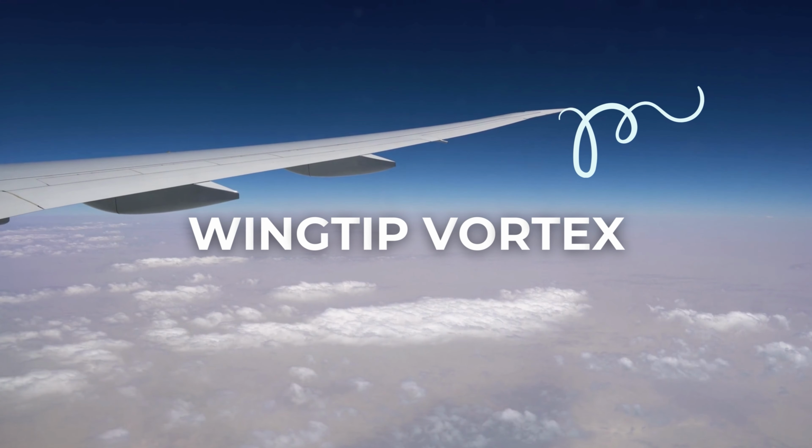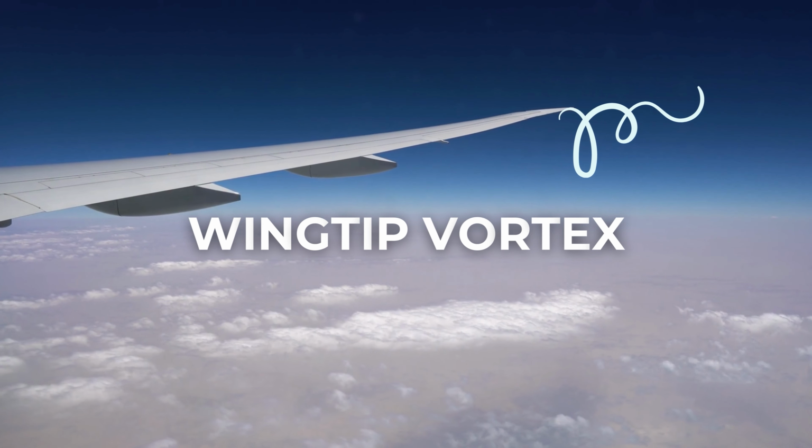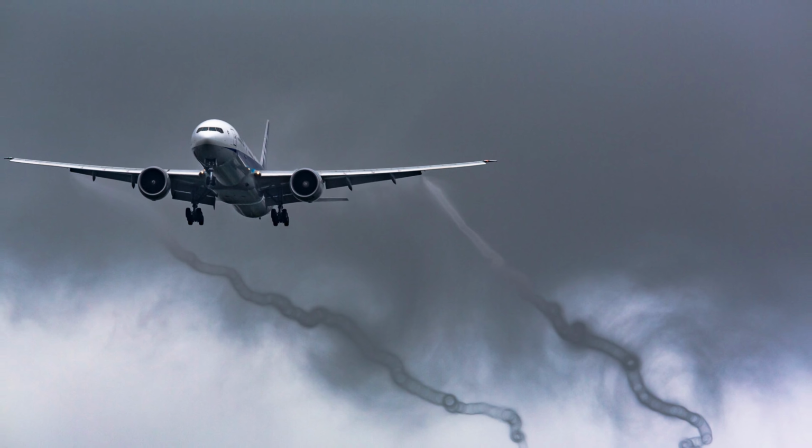The vortices aren't just confined to the wingtip, though. The rotational movement of the air has inertia, and it continues to spread out behind the wingtip. The vortices increase in diameter but decrease in intensity as time passes. These are called trailing vortices, and they extend for quite a distance behind the aircraft.